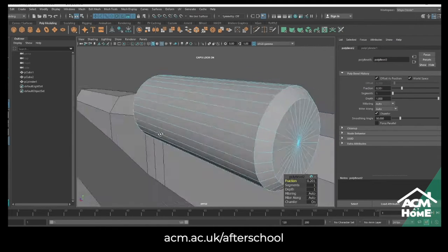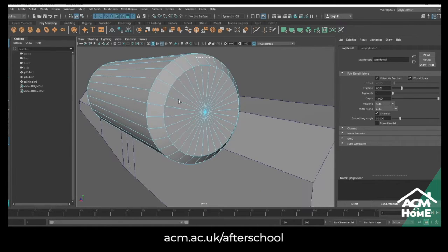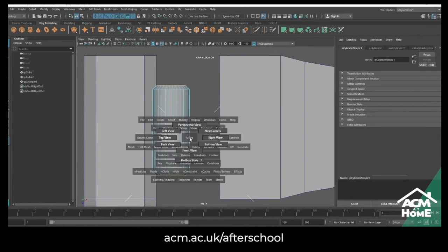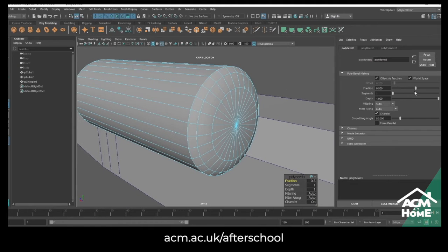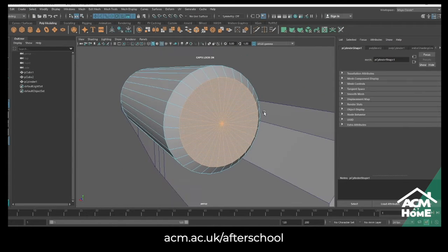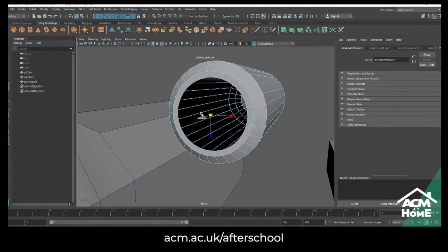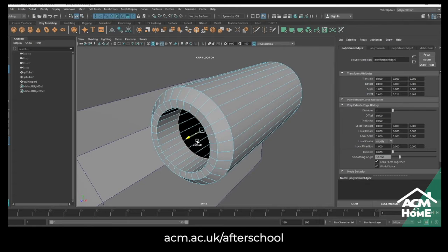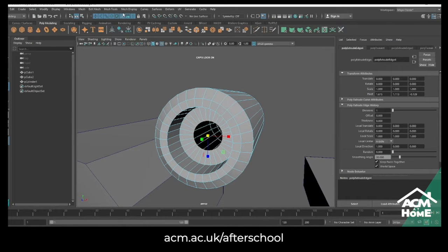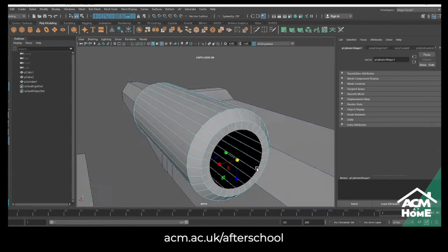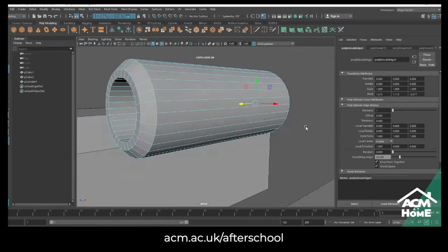I selected one part, inverted the selection and then chose to bevel the top. It's a quicker way of getting that effect because you can kill two birds with one stone, essentially, and then doing it again. If you want to select specific faces, but there's a lot of them, usually you select the opposite and then invert the selection, or select the easier parts or components and then work from there. Similarly with extrusions, when you're editing things, it's a good idea to use extrusions in order to manipulate shapes.